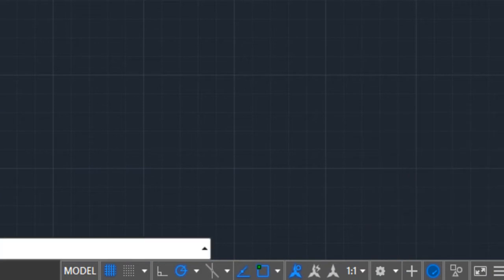Then what we are doing is we're drawing in 3D. We are no longer drawing in 2D because this is 3D modeling. So you have a choice. Either you can look up top and change it, or we can come down here to the bottom to the gear, click it, and you're going to want to go to 3D modeling, not 3D basics, 3D modeling.